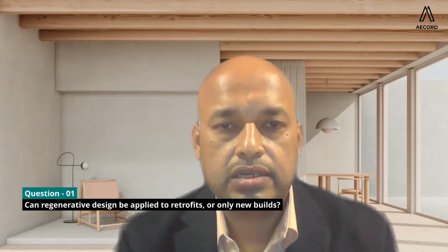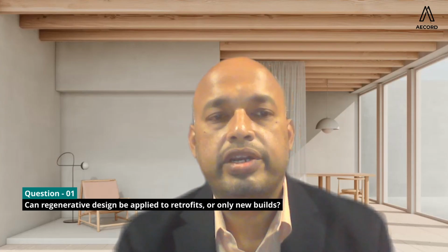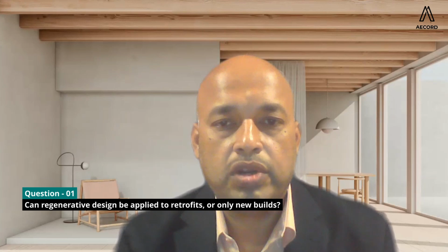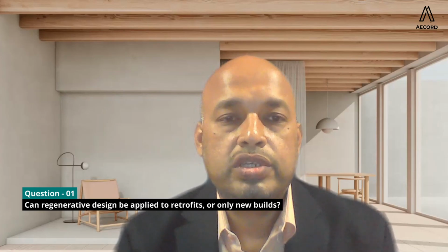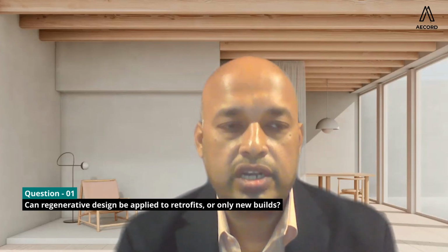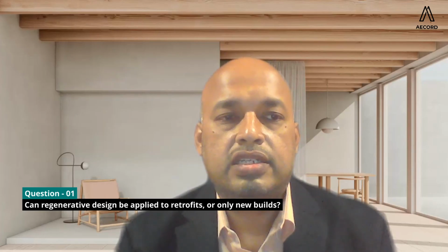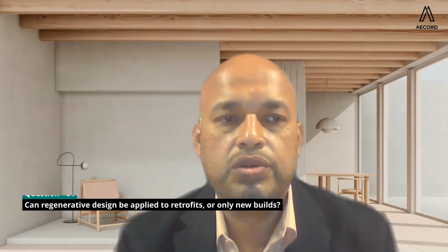There is a catch here. If you want to keep your architecture and facade the same, and you want to get into regenerative, you can do it. Regeneration, or giving back renewable energy to the grid, you can still do, but in that way you will not be optimizing or reducing the cost impact, because already your building is inefficient. You have a lot of heat load coming into the building, daylight not utilized, and still you want to get into regenerative renewable energy. It's a big no. First you need to handle the building facade, increase the daylight, reduce the heat gain, and optimize your HVAC system and lighting system.